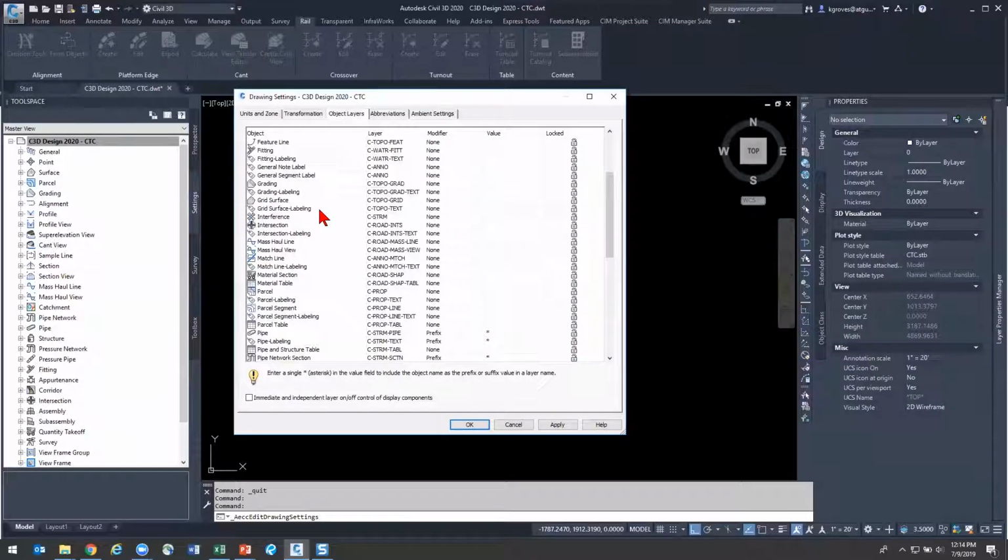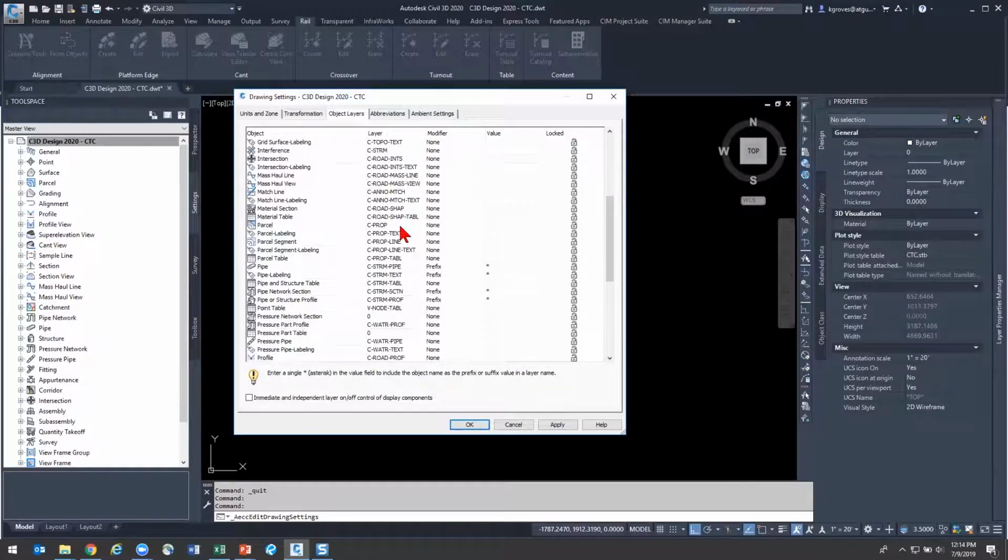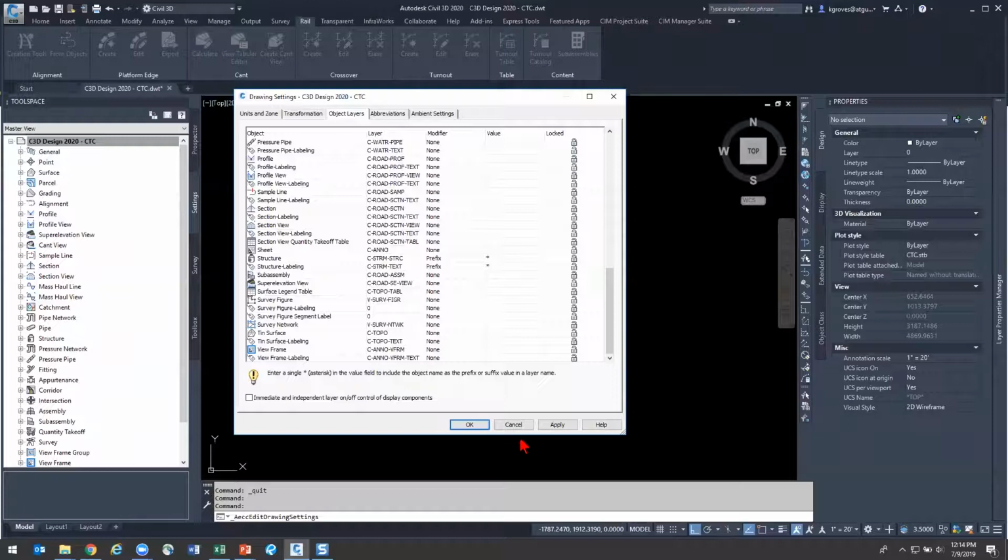And if you start your template from the out-of-the-box AutoCAD Imperial, AutoCAD Metric, and CS template, there's going to be a lot of this information filled out. But if you're ever wondering, did I start this template from acad.dwt, the base AutoCAD template? You'll be able to figure that out because you'll notice that all of this layer assignment is set to 0 because the AutoCAD template doesn't know what a civil 3D object is and can't push that information forward.